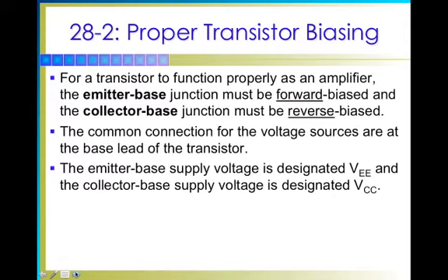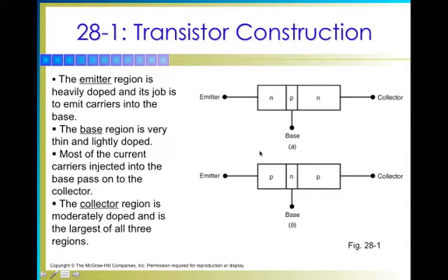All right, so let's move on to our next one. It says for a transistor to function properly as an amplifier, the emitter base must be forward biased, which I already described to you, and the collector base must be reversed. Let's go backwards just a minute. The emitter base junction, they're just talking about this part right here where N and P connect up, where the emitter base junction must be forward biased just like a regular diode. And secondly, the collector base is reverse biased. But now notice down on the PNP, it's opposite.